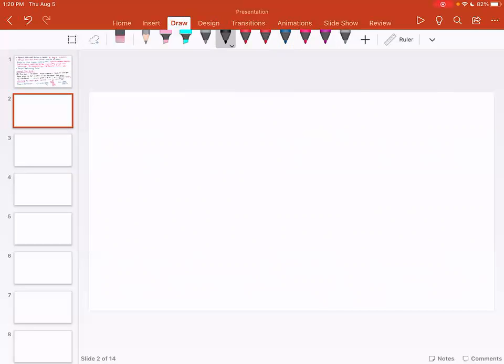So remember the note, when gear and pinion are made with the same material, we design the pinion. Perfect. The pinion is the small gear.